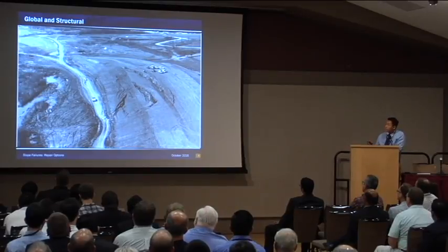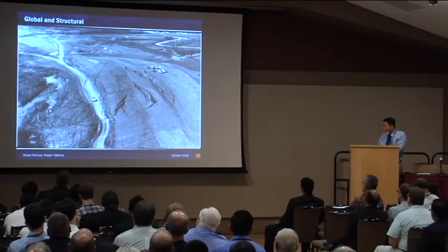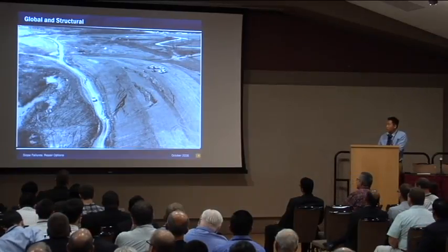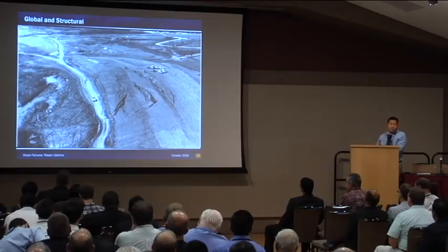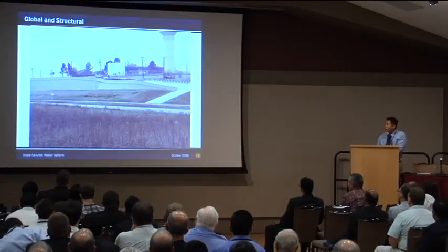For the repair for this type of slope failure, first, you can remove and replace with a better material and compact better, or you can install a wall system, either a cut wall like a soil nail, or a sheet piling wall, or you can put a retaining wall in front and make the front slope or the back slope flatter. So that is the recommended repair option.